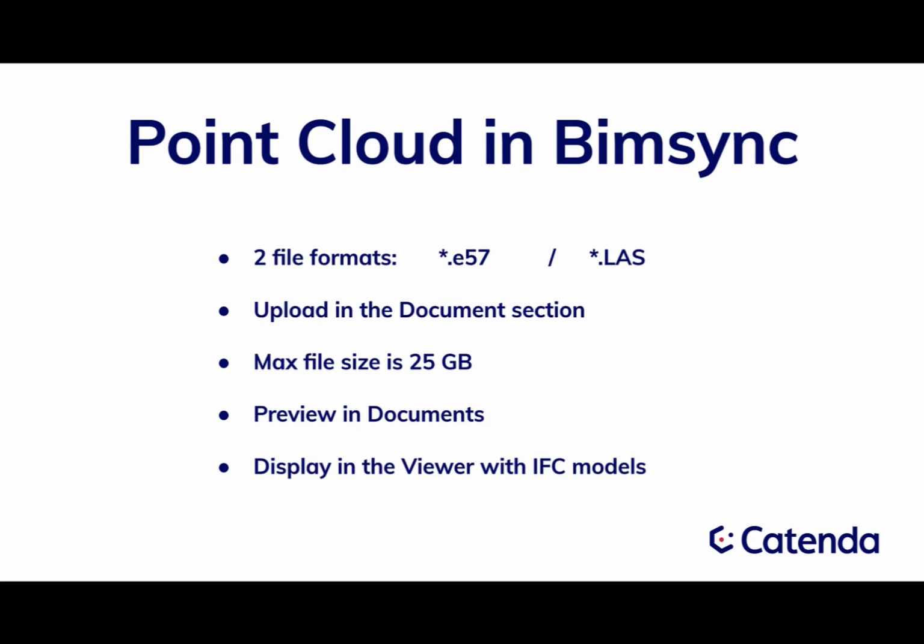The way it works in Bimsync, even though I will demonstrate it to you later, is you upload in the document section. That's something to be very aware of. You will push your files, E57 or LAS, into the document section. We have now implemented a file size limit for several reasons. One being the uploading time, because if you have a large data set, you can run into trouble sometimes uploading it to the system, thanks to some network limitation, I would say.